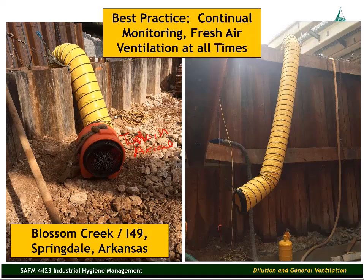All you have to do is turn the fan around. And the collapsible ductwork that we're using here, it's set up in a blowing configuration now, but if you wanted to set it up to remove air from the space, you just turn the fan around and hook up your ductwork, your flexible ductwork, and you're good to go.